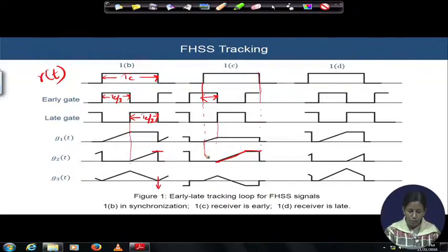Now, a funny thing is happening at the output of the adder. See the timing diagram at the output of the adder slowly. From this period to this period, the adder has got a positive value. Then the adder has started getting the negative value, and as the peak value of the negative voltage was higher than the positive one, it will definitely cross the zero axis, end up with a negative value, and hold that value. So, you are getting some negative voltage at the adder output here.